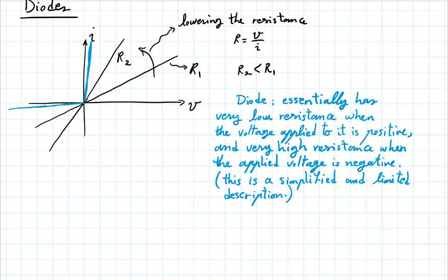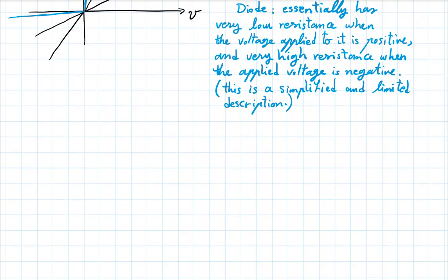Now, if you have something like this, think about the circuit that we discussed before. If I have that input voltage being the sinusoidal voltage that we just talked about, and this is how you show a diode. And if you put this capacitor here, imagine the capacitor is initially uncharged. As soon as the input voltage rises a little bit, you're putting a positive voltage between the two sides of a diode. And the direction does matter. You have to pay attention to the schematic. You see it has an arrow. And that's the direction in which it would like to show low resistance or pass a high current.